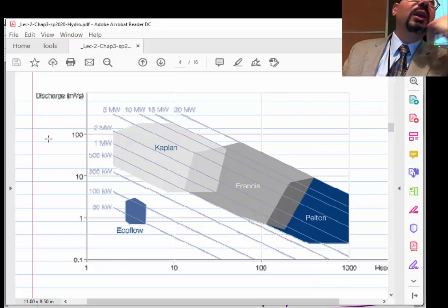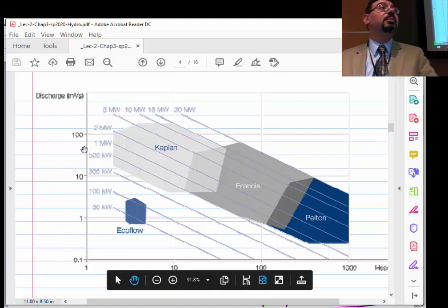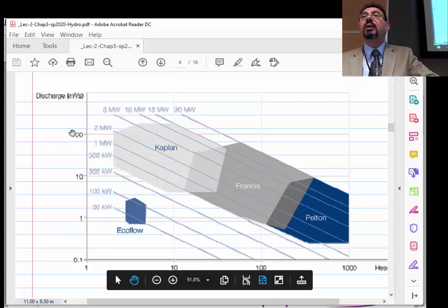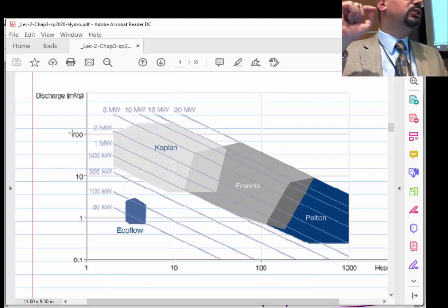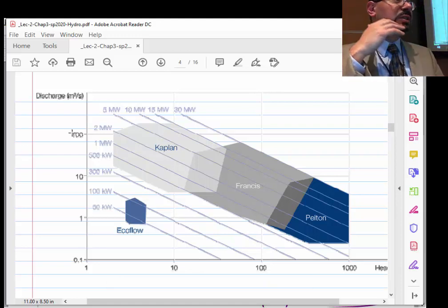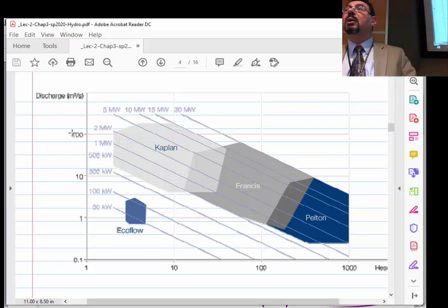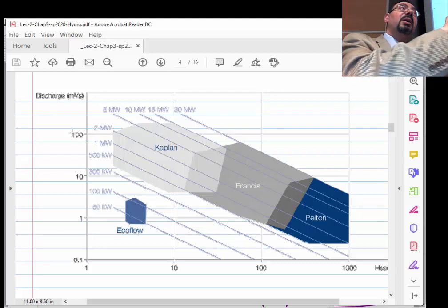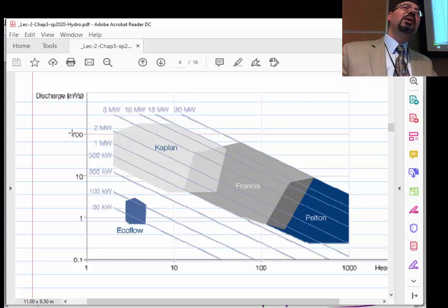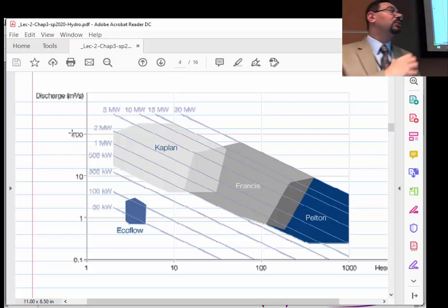But also interesting, the flow rate. Kaplan is like all axial machine. They can deliver huge flow rate. And that's the same thing for jet engines. If you look at jet engines from World War II until now, you'll see that in the old time, they didn't have that much flow rate, so the compressors were radial compressors. But as the engine got bigger and bigger, they could not do radial compression anymore. They have to switch to axial compressor. Why? Because axial machines have higher flow rate.